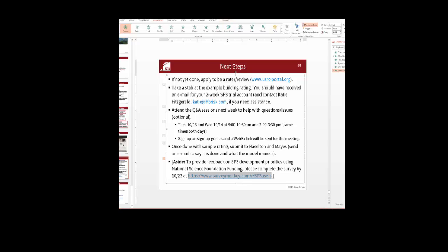And then on the component side, you would just have to go in and swap out the structural components, and put in your Frankenstein structural components in terms of what's in your building. So I think it's important for the more complicated systems, Kurt, that people understand the simplified method's going to have its limitations. Yep. And when we get to the more complicated framing systems, I think we're going to have to seek to get mode shapes from an analysis, because there's only so far you can go with a simplified method.